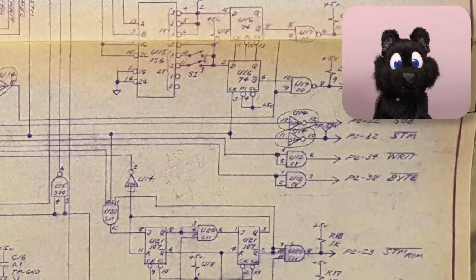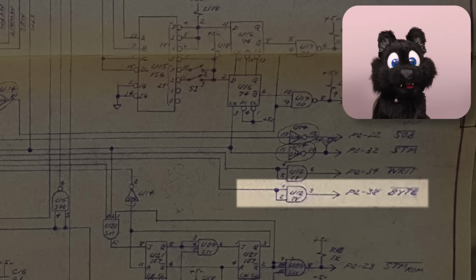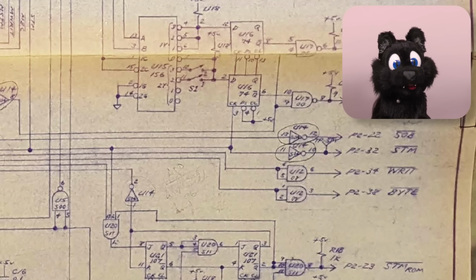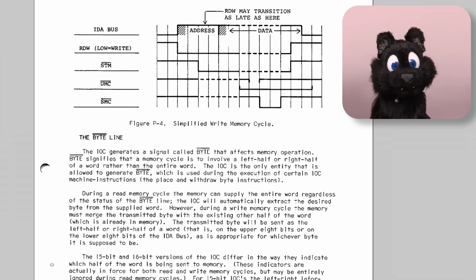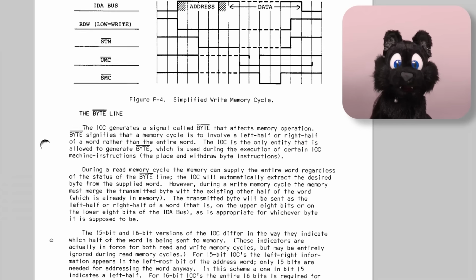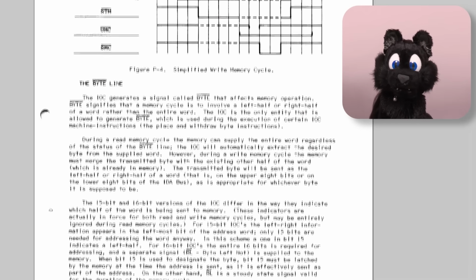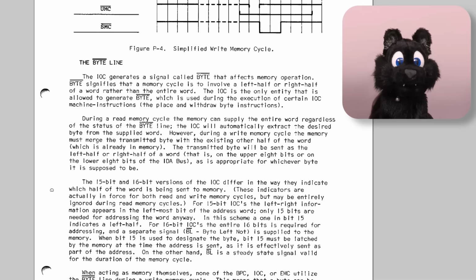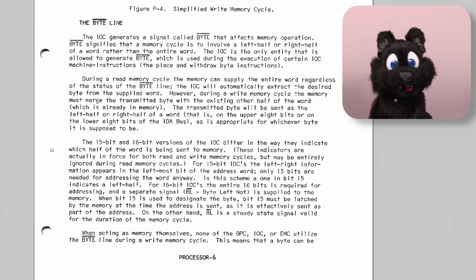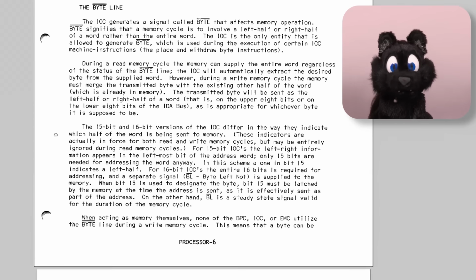If it is signaled, the CPU wants the upper or lower 8 bits of the addressed words only, depending on the A15 address bit. For the reads, this can be ignored since the CPU only takes what it wants anyway, but for writes, it would destroy half the word in RAM with random data if you don't honor it.